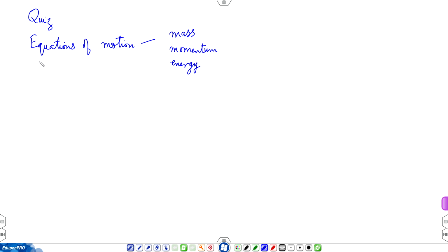So, we looked at local approach, global approach. And right now, we are pursuing a global approach involving a control volume formulation. So, here we distinguish between near field and far field. You do not have to, because you can pick any control volume you want, but if you choose the control volume carefully, then the integrals can be estimated reasonably well. That is the idea.